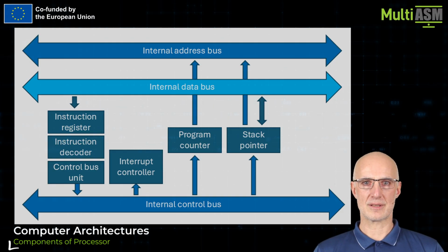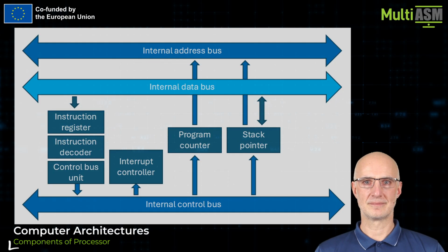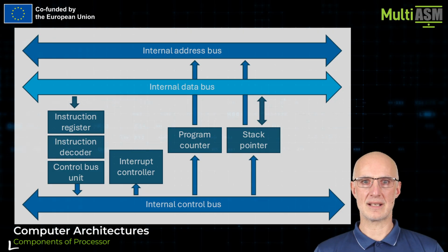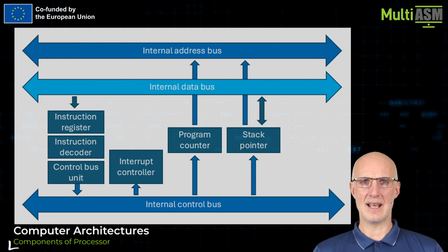The processor stores the instruction code in the instruction register and, based on the bit pattern, interprets what to do next. And if the instruction requires the execution unit operation, the control unit generates signals to control it. In cooperation with the execution unit, it can also need data, read from or write data to the memory.